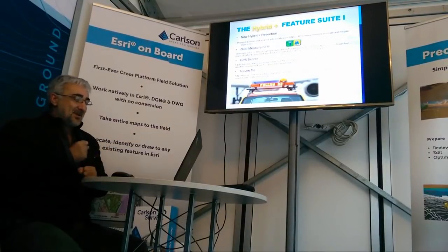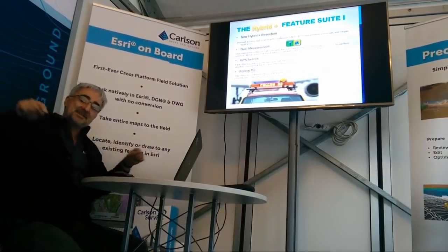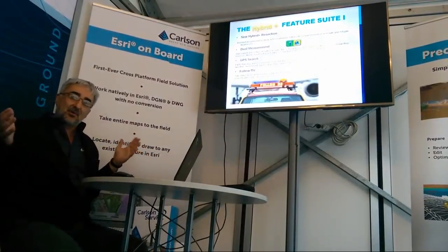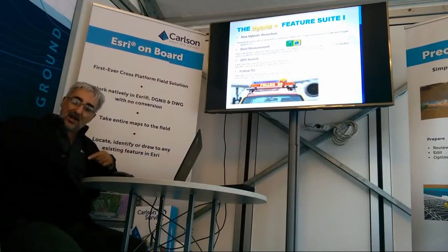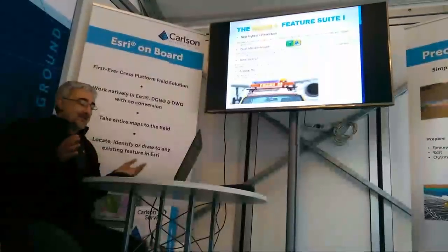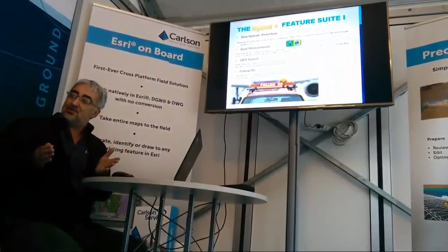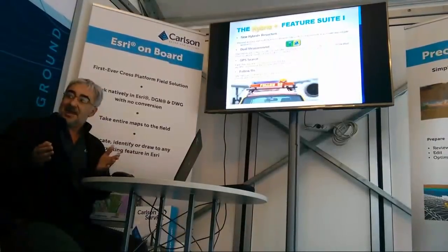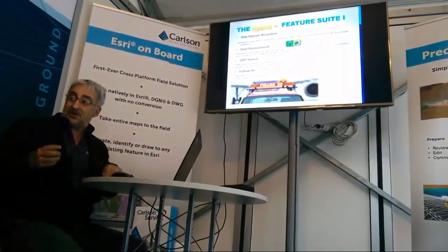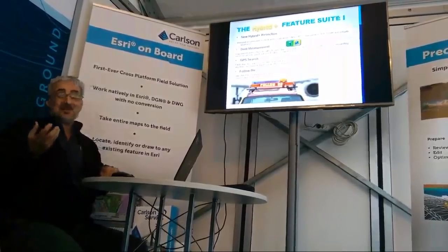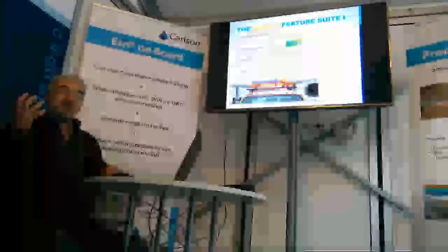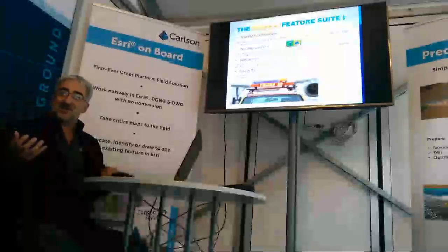It's typical that if you choose a good distance, let's say more than 40, 50 meters, and good angles, 3-4 points, good angles, you typically get a few millimeters closer to the resection. And not only position, but orientation, very good orientation every time you do a resection.